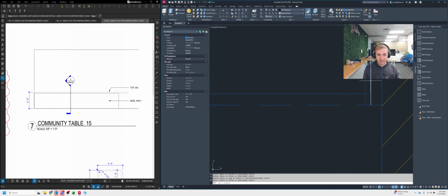But the reason why this is important is because this is the stop of the panel. And we're telling AutoCAD where that panel stops by bringing this out that 1/8 of an inch, or half the width of the 1/4 inch reveal. Let me make sure I got this right too. I just want to make sure I didn't mess this up. Okay, I got it right.